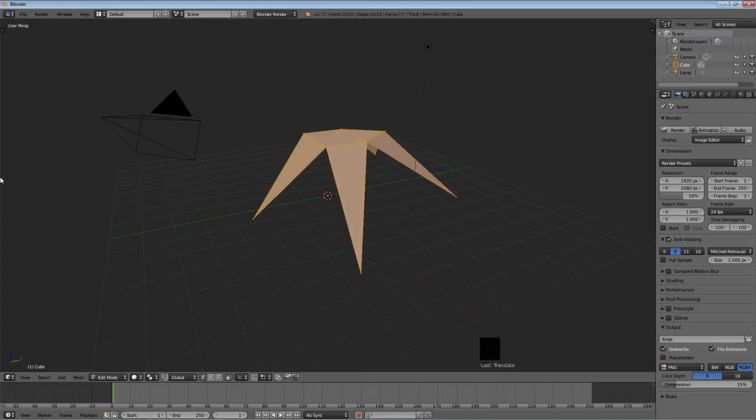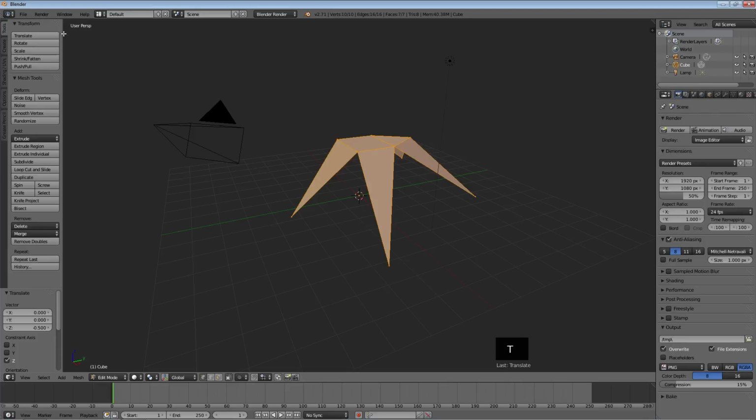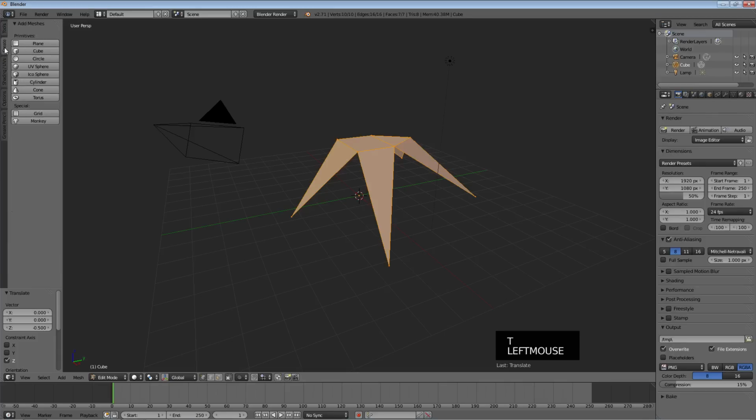You should, after this video, have a basic grasp on how to, number one, manipulate the 3D view window. Number two, add a mesh using Shift-A to add, and that'll add on where the 3D cursor is. Or you can hit T and go over to Create, and you can add things from here.